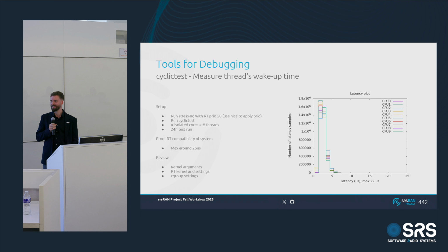Yeah, I can take that. So in this talk and in general, O-RAN has adopted open fronthaul, the O-RAN open fronthaul interface for connection between RU and DU. So it's eCPRI; while it's the basis for open fronthaul, it basically provides the framing sitting on top of Ethernet, and then it's following the O-RAN specification.